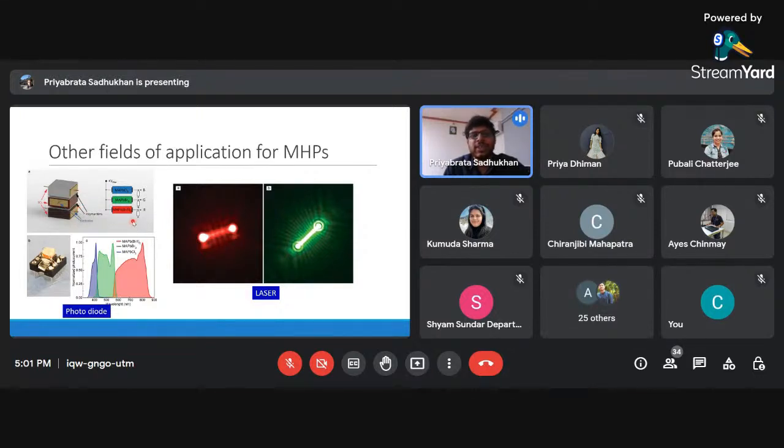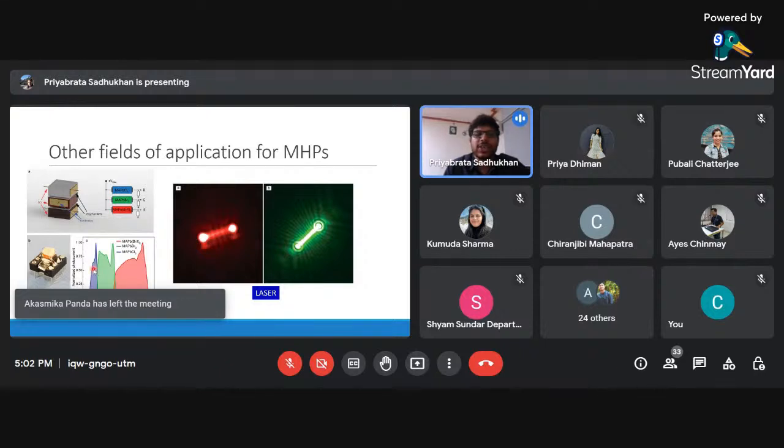But for perovskite, due to their very good optical properties, we can use the perovskite crystal itself without using any filters. We can directly use the perovskite crystal, because they have different band gaps, and different band gaps mean they have different regions of interest in the wavelength spectrum. You can see here that 3 different perovskite crystals are stacked one upon another. First one is the methyl ammonium lead chloride, then the bromide, and then the iodide.